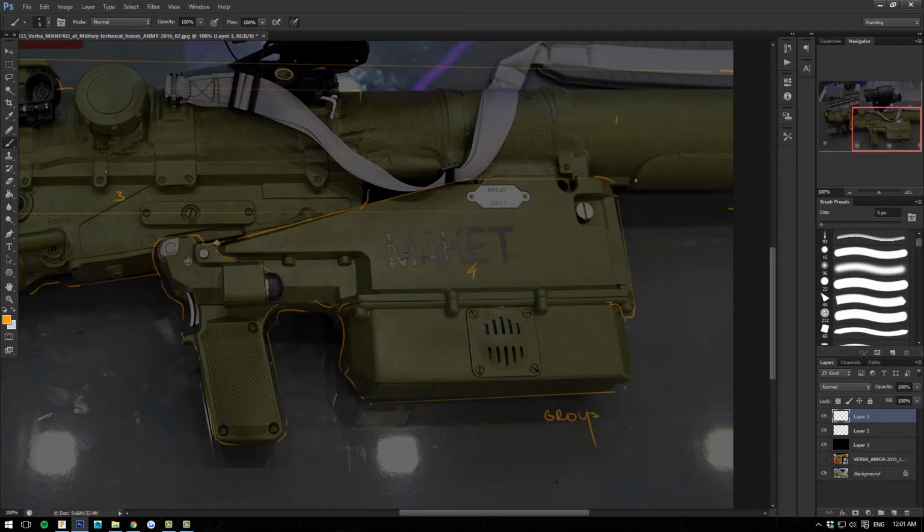What we can do is find a plane that's going to be just coplanar with this, right? And we're going to sketch the overall shape, which overall shape in a form of a sketch will look like this. This is not going to be present yet. We're going to cut that out. And then in this particular case, we can sketch the slope right away. So this is what our sketch is going to look like.